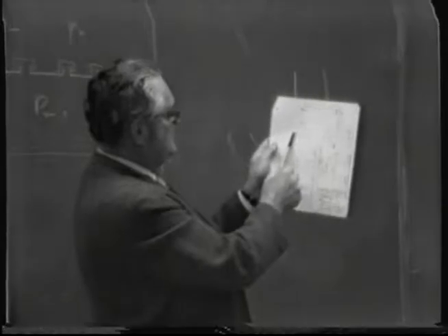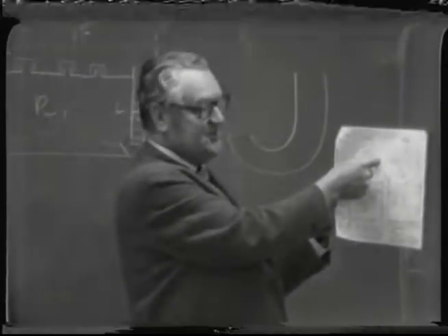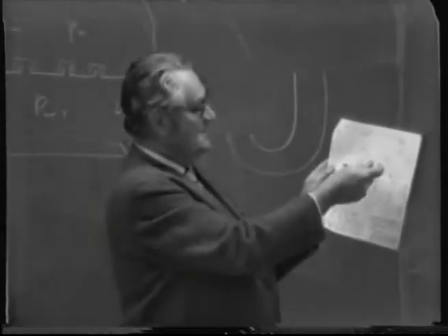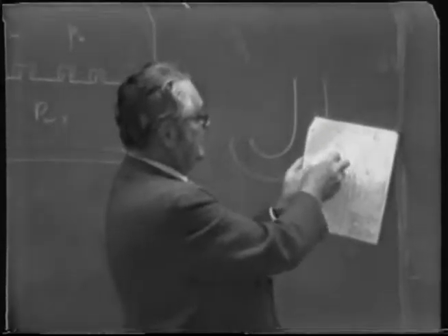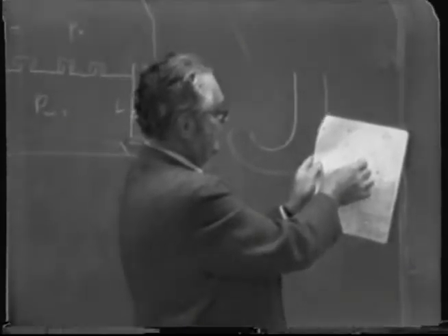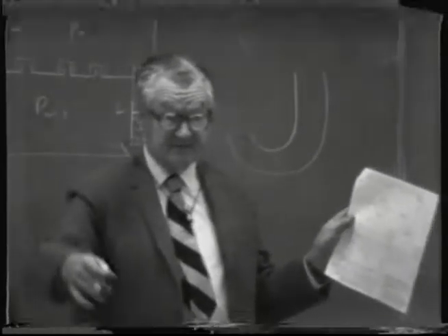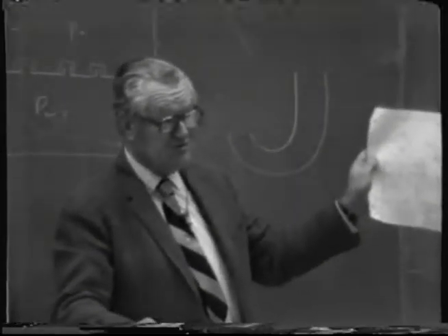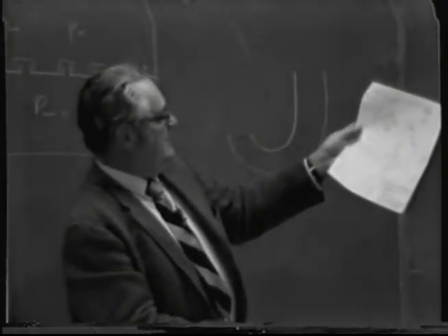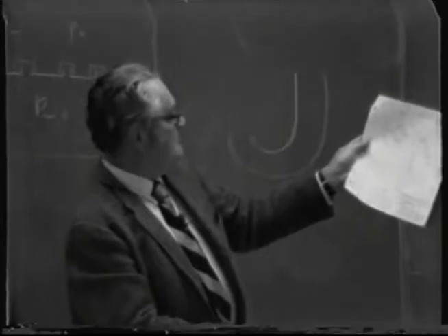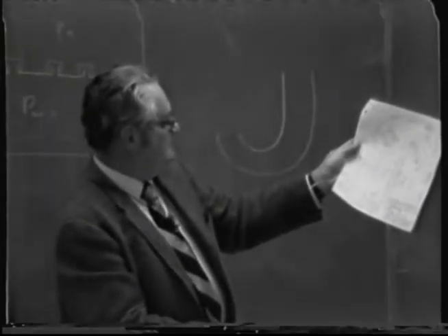Well, first of all, you see they have a very short path to travel because they're located out here somewhere in the middle of the column. So naturally, liquid's going to flow the shortest distance. It'd flow from here over to that one, and from that one over here and right down. And so you'd have a large perimeter area here that's inactive, the so-called shaded area. So it's a poor layout as far as that's concerned.